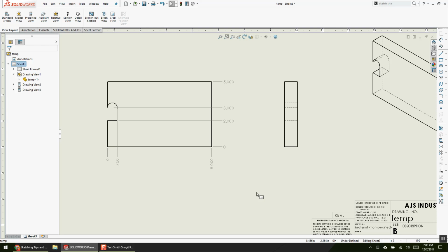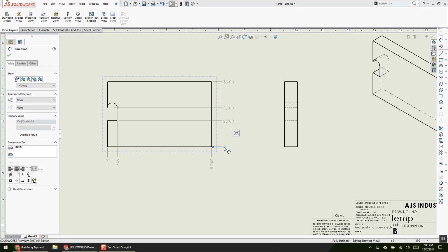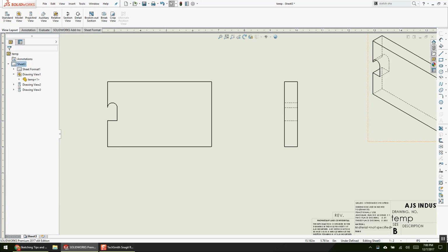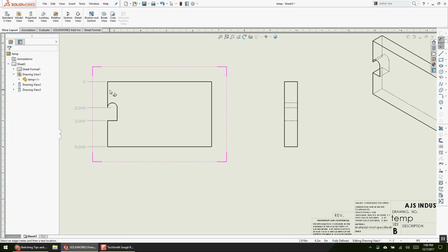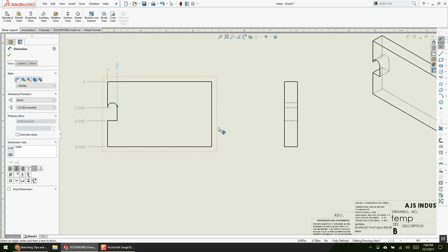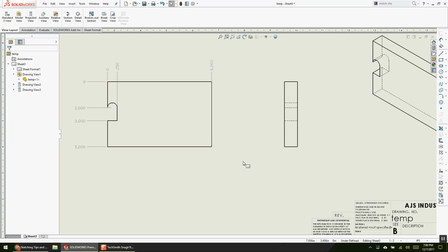Now, I mean, there's a whole conversation to be had if it's a CNC and do they really use the print and a bunch of other things. But universally, you're going to put the ordinates top left. And the only exception to this is if you're going to flip the part enough times and you need to maintain your universal zero for accuracy. But if it's a hole to hold a bracket to hold a sensor or something, right? You don't really care, so then you can just keep doing that.